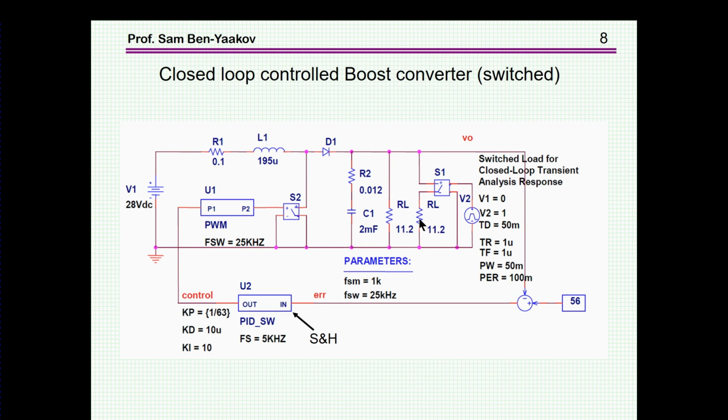Now let's have a look at the actual simulation of, in this case, a boost converter. This is a simulation in the time domain, a switching circuit. I'm not showing all the details because this is a little bit outside of the subject matter of this presentation. What it is, we have here the input inductor. This is a generic switch, a diode. This is the output section. Here we have a means of loading, a step load to the output to see the dynamics.